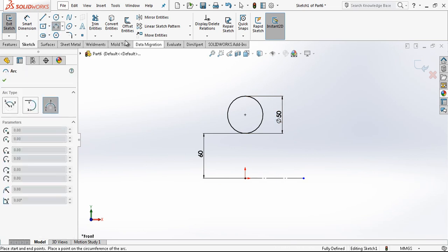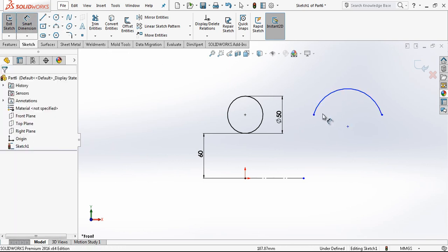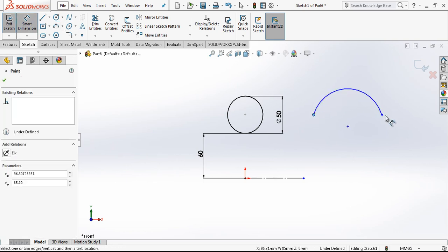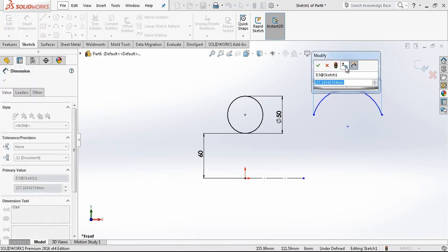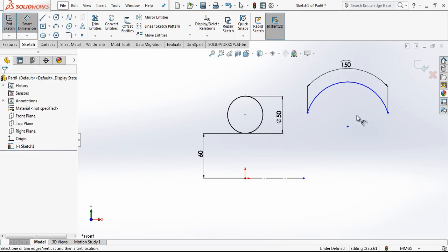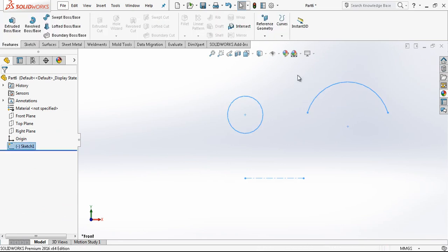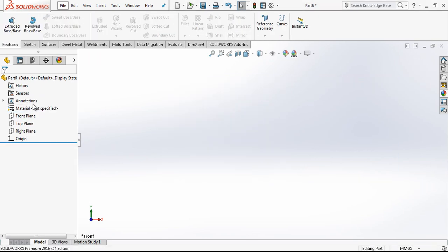And I'm going to show now arc dimensioning. To find the arc length on your part, you should choose your semi arc or quarter arc. It can be in any degree. 2 point, and then clicking on your sketch on your arc itself, and then as you see, we can say 50 millimeter arc. This is our option.